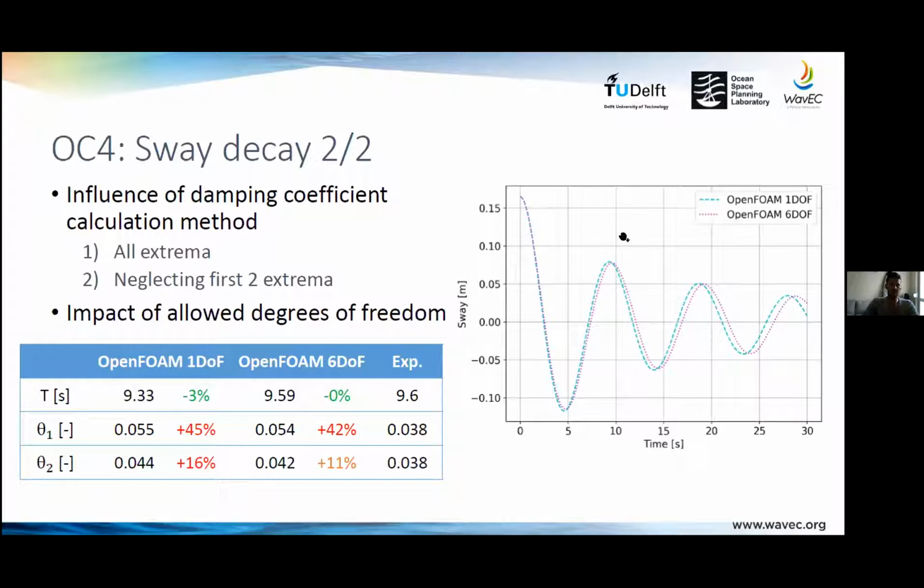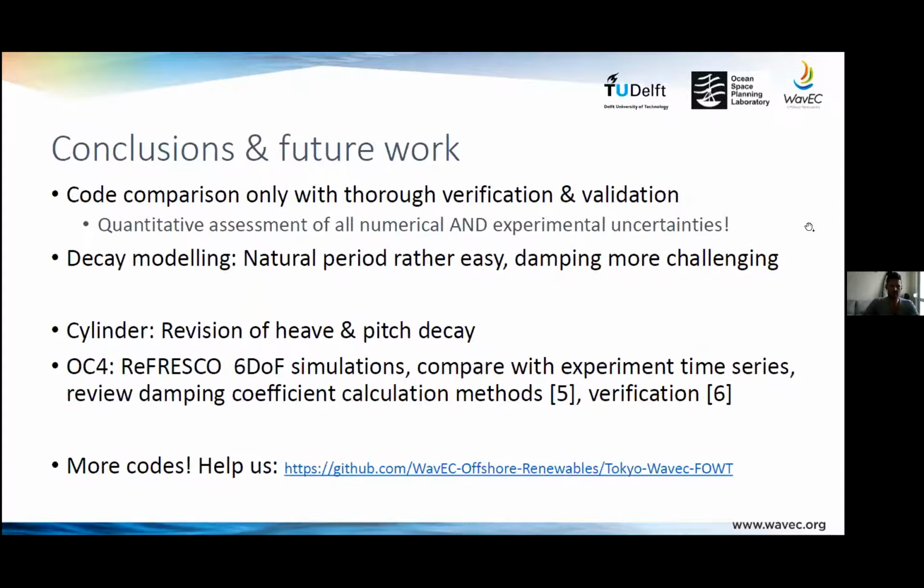It's better to use as many degrees of freedom as possible, because the calculation of a few more equations of motion is really not computationally significant for the million cells for which you solve the Navier-Stokes equations. So more degrees of freedom always helps.